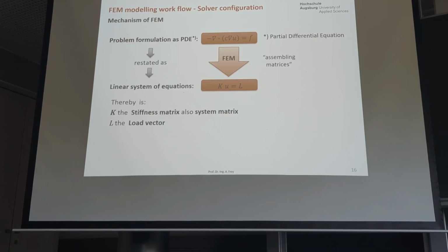So if you have a heat conductivity which is not just a number, but itself depends on the temperature, then it would be nonlinear. Same thing with electrical problems. If the electric conductivity is just a constant, it is linear, but it is in many cases true that the electric conductivity is temperature dependent. With increasing temperature it can go higher or lower, NTC, PTC behavior. That makes it nonlinear.